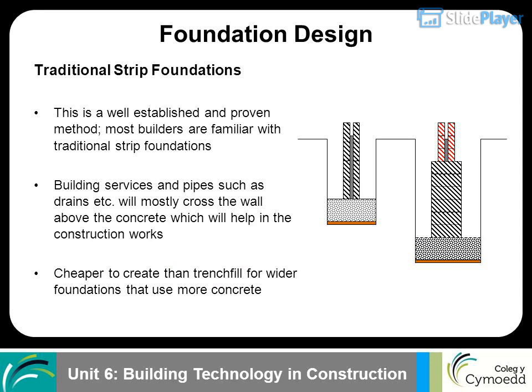Foundation design. Traditional strip foundations. This is a well-established and proven method. Most builders are familiar with traditional strip foundations. Building services and pipes such as drains will mostly cross the wall above the concrete, which will help in the construction works. Cheaper to create than trench fill for wider foundations that use more concrete.